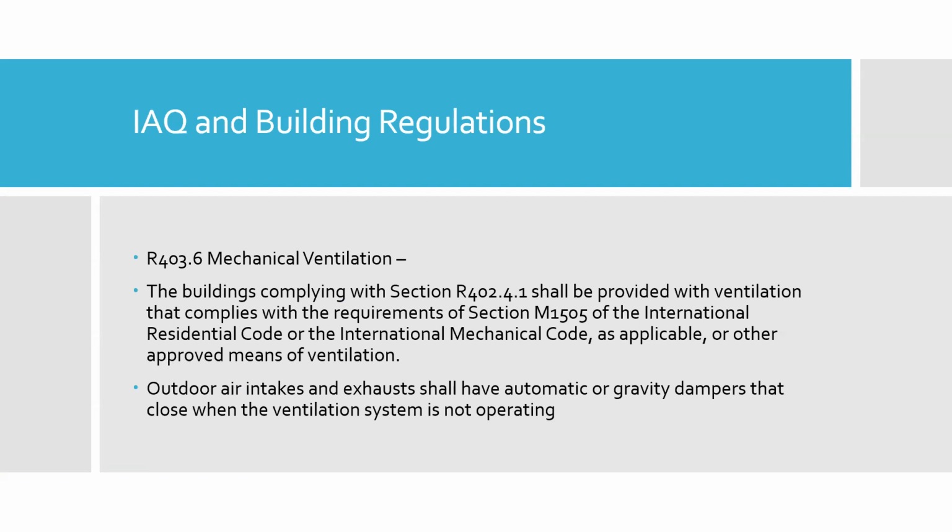So I know when I did inspections a lot of builders would look at it from, we want to build a tight house, but now we want to punch a hole and call that mechanical ventilation. And now it doesn't make sense. Why are we going to build a tight house and not allow the house to breathe? Why are we going to build a tight house and then punch a hole in the outside? And the answer to that is we want to control how much and when. So it's not uncontrolled contaminations or humidity or temperature coming in and out of the building. We're going to conserve energy by trapping everything, but now we're going to make sure mechanical ventilation is there to either dilute or exhaust the contamination inside the house.